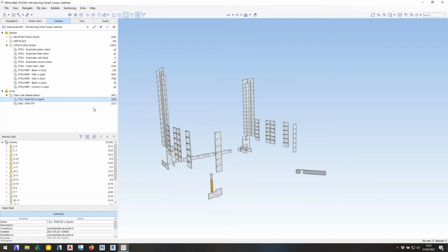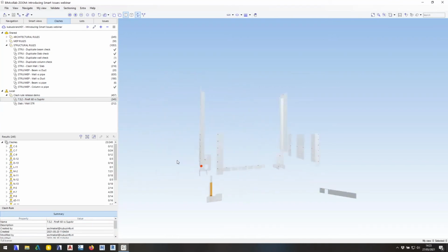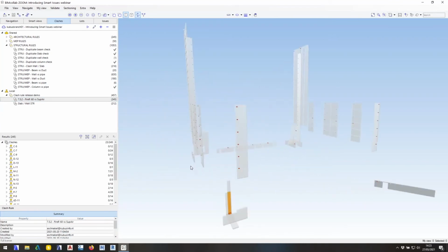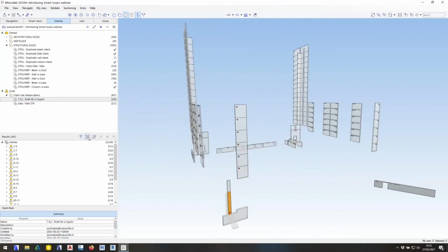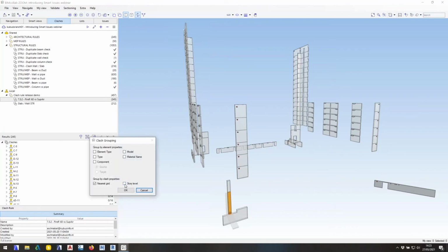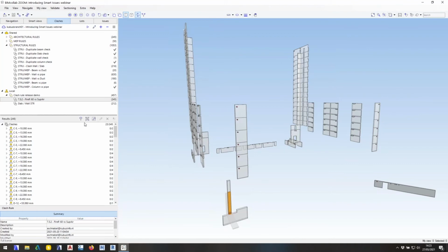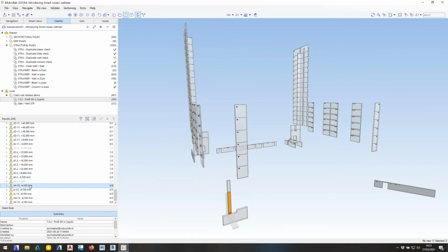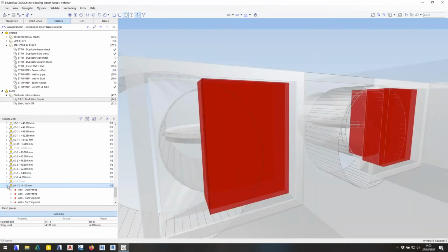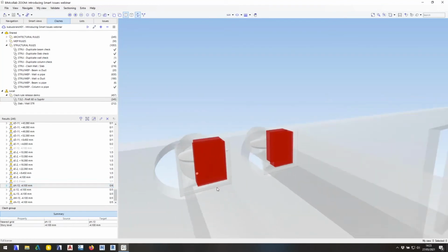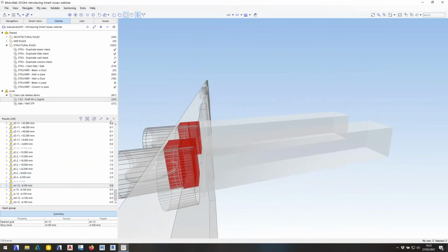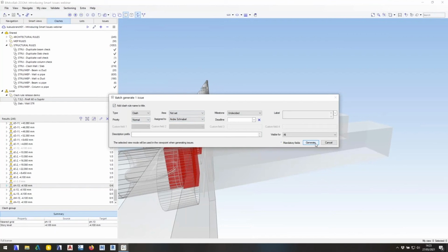So I have one of my specialized MEP rule sets here, giving me again multiple clashes, and I can even use a different grouping mechanism to focus clearly on my task, which might be certain clashes on certain levels for today. So I can investigate the clashes on level and on grid grouping, and report as we go along.